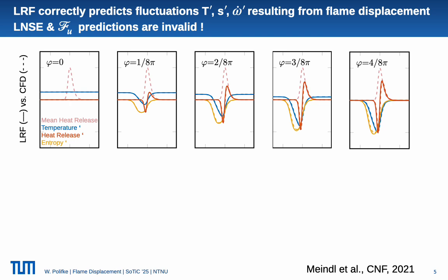The later half of the period, when the flame is convected back to its original position, you would see the same images, but simply in reverse order. The entropy also shows the typical decrease, the dent, so to speak. Temperature is a bit more complicated because you also have modulation of temperature through pressure, in isentropic fashion, so to speak.